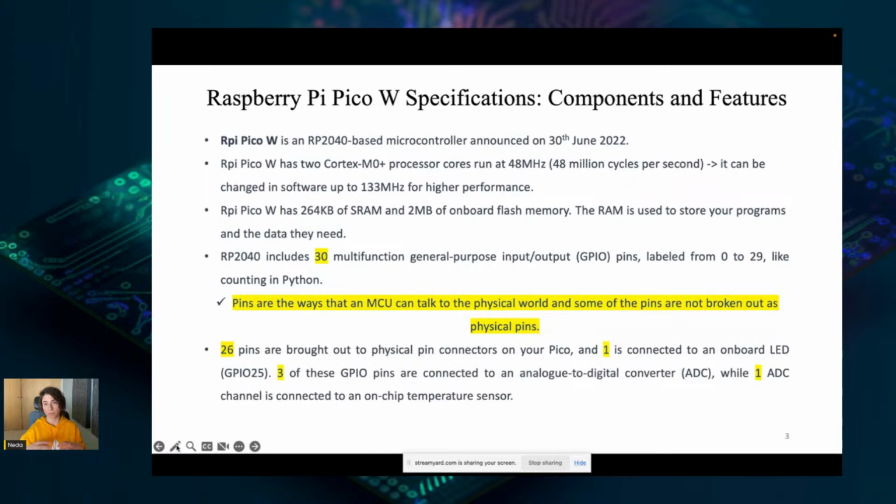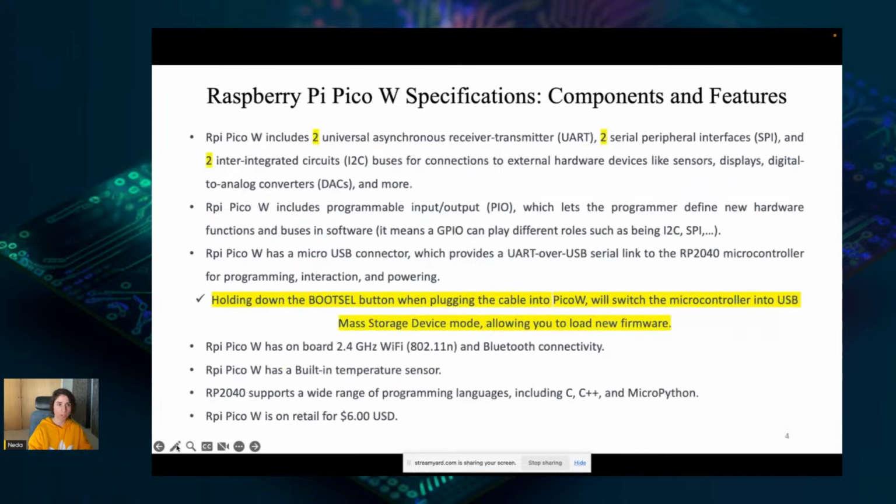That is why we will see in the chip that there is a gap in the numbering between the last basic general purpose pin, GP22, and the first analog capable pin, that is GP26, and we call it ADC 0. And I will show you in the next slide how the chip looks and how the numbering is.